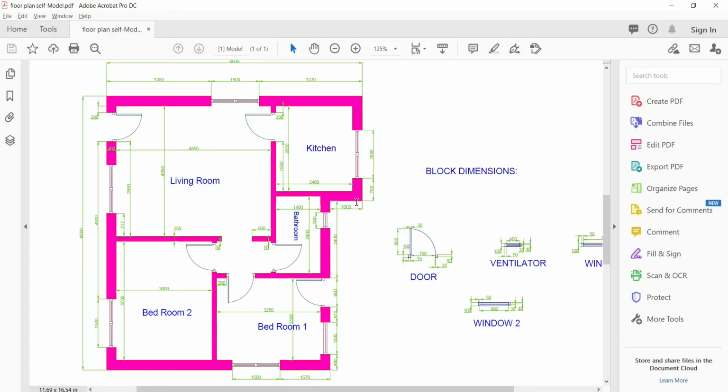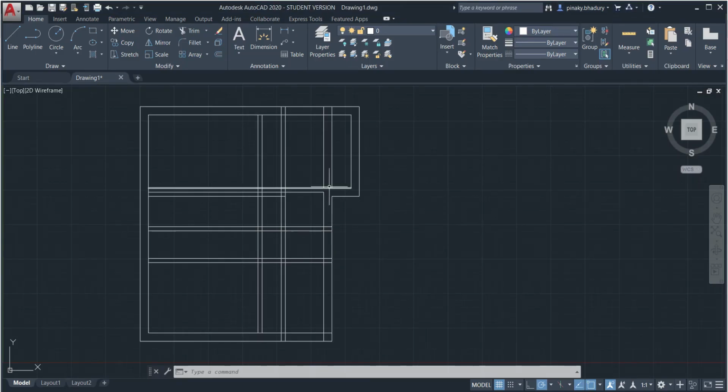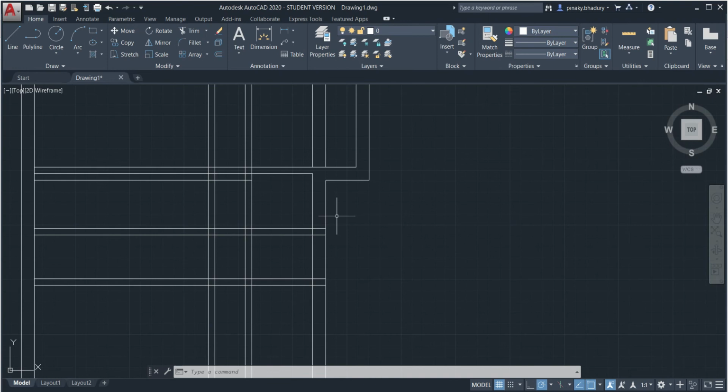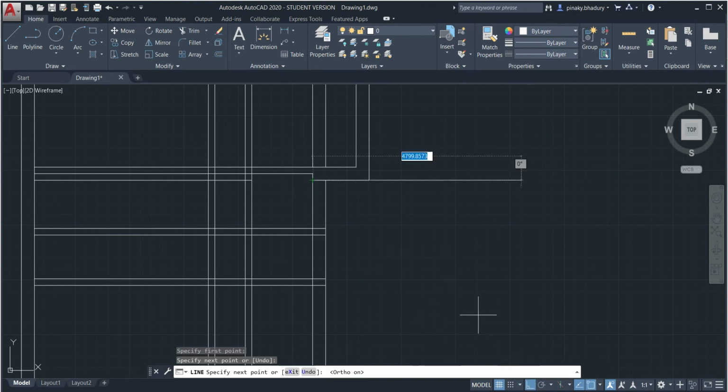The next thing is we will construct another part, that is we will trim another part. So as you can see here, this height is not given. Let us consider this is 700 height, this we can consider as 600. Okay, so if you want to select this as 600, so one thing what I am doing here is I will draw a line from this point to this point. You can keep the ortho mode on if you require to. I'm keeping the ortho mode on here.